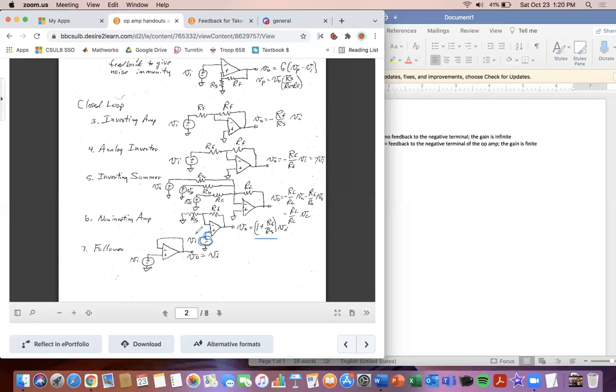And the reason why it would be non-inverting, if you think about the original equation where we had gain times VP minus VN, we know VP will be greater than VN, since VN is hooked up to 0 volts here at ground, but VP is hooked up to this voltage source here. So this will produce a positive number, and a positive number times the gain is going to result in a positive number, because gain will be positive. And so for a non-inverting amp, its voltage source is hooked up to the positive terminal, and that causes it not to become an inverting amp.